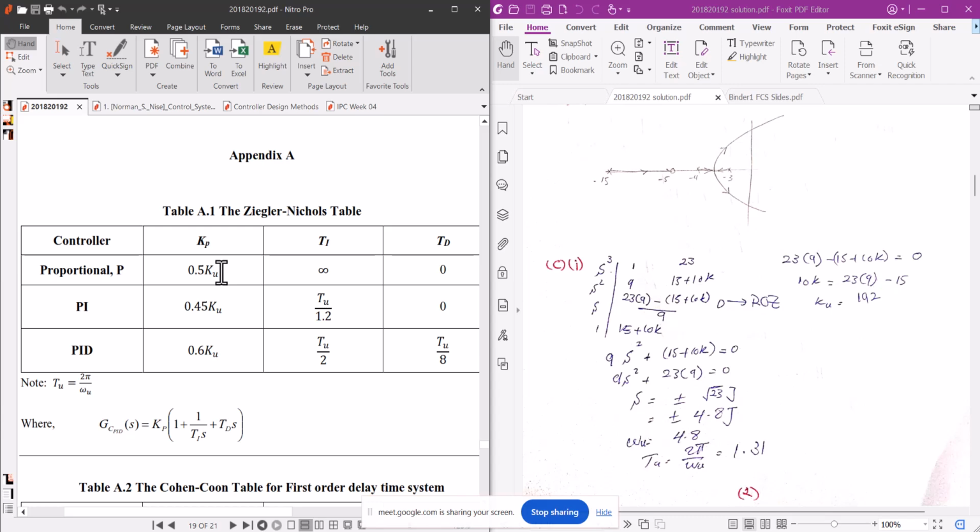through the classical control method. We also do this practically in the industry. We keep on increasing the proportional gain, and at one value of the gain the system becomes oscillatory. That gain is called the ultimate gain. Now in the question, how will we determine this? We will determine this through the Routh-Hurwitz table. We will make the Routh-Hurwitz table of this closed loop system with only a proportional controller.